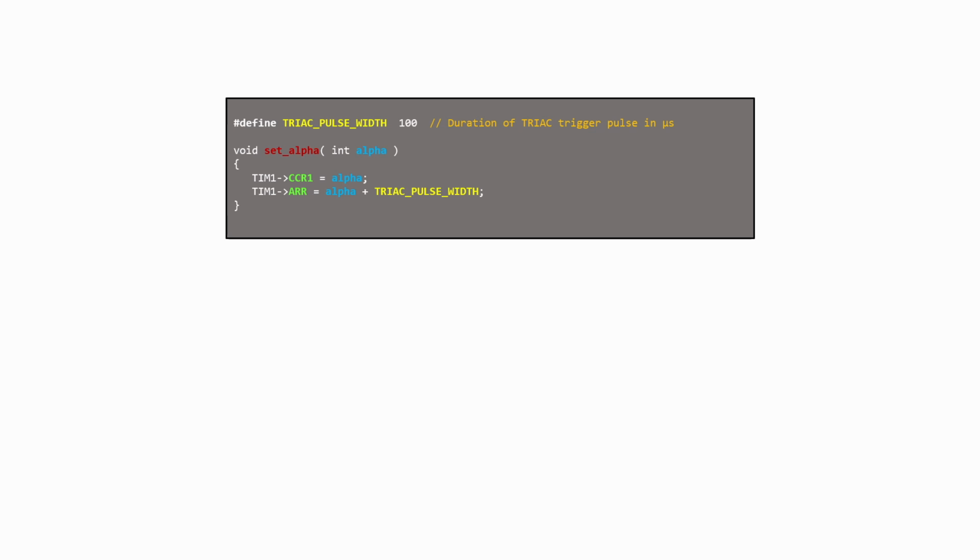Unfortunately, as seen earlier, there is no function available to calculate the necessary alpha value to generate a certain normalized output power. That's why we need to use a different approach here. First of all, let's create a table that contains the resulting normalized output power values for all values of alpha from 0 to pi in 10,000 steps.